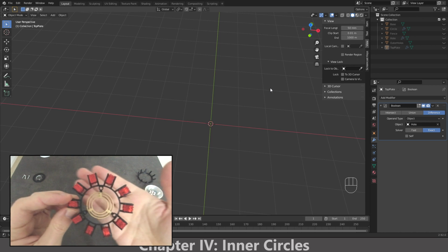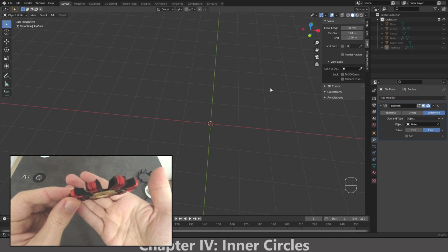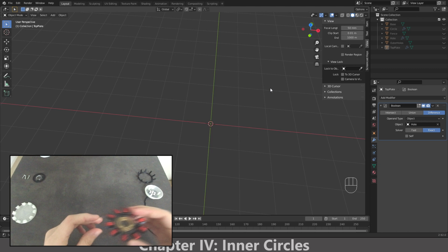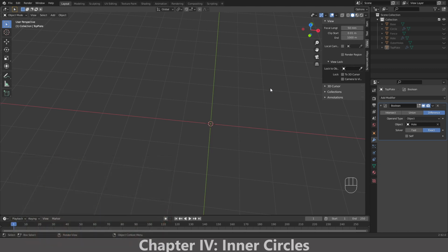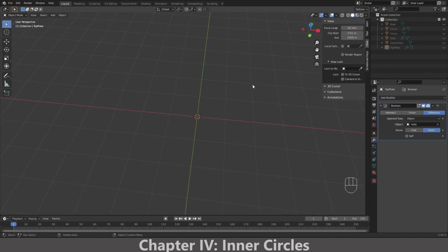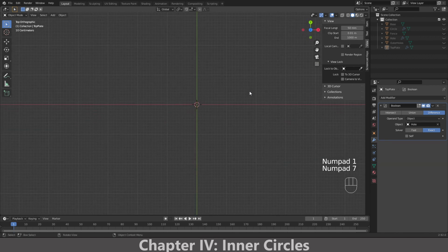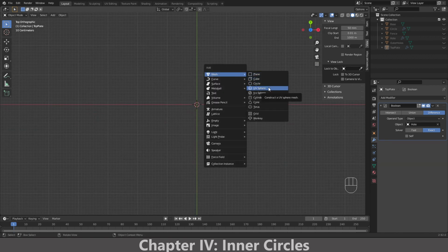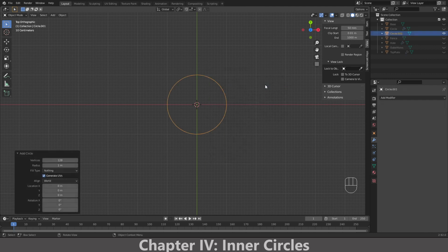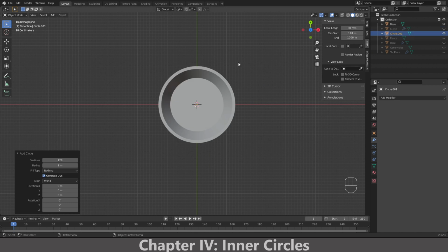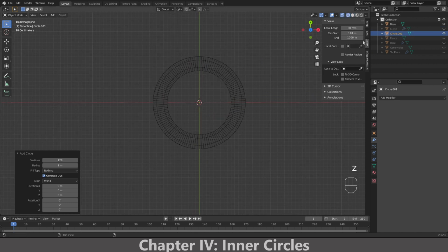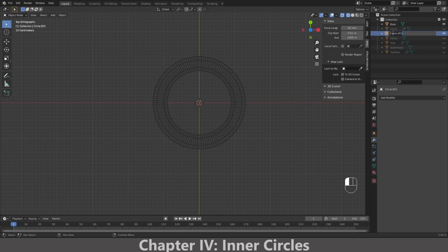Now we will continue with the fourth object, which somehow looks like a candle stand. This basically is a combination of multiple objects. We have here 4 circles. First we will create the inner circles. And I will create again a circle object. I make the base object visible again, and I go into wireframe mode. Then I select my circle. I call it inner circle.